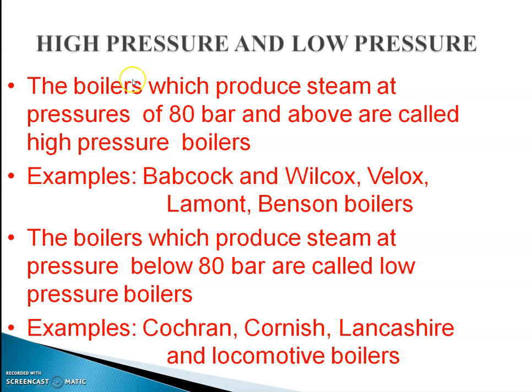Depending upon the pressure rate, high pressure steam is formed above 80 bar in the high pressure boiler, and below 80 bar in the low pressure boiler. Boilers which produce steam at 80 bar and above are called high pressure boilers. Examples: Babcock and Wilcox, Velox, Lamont, Benson boilers.